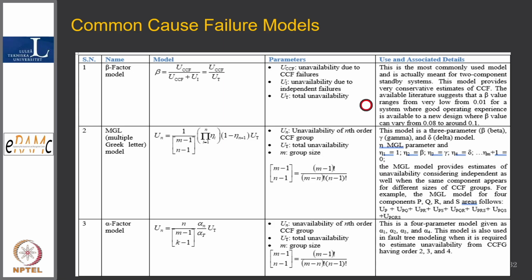But to me, it is more important that we understand detection of common cause failure in prognostics and health management. We should develop different sensors, like for plant humidity going above a level, which we know is a source of common cause. We should have a sensor in the plant which tells us the humidity has gone from 50% to 80%, or we should know that a water level rise can affect all the breakers in the system because of shorting.